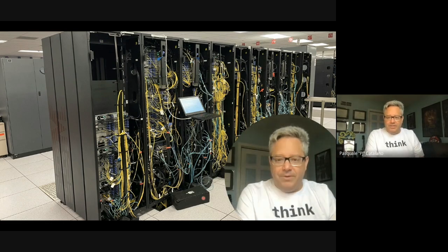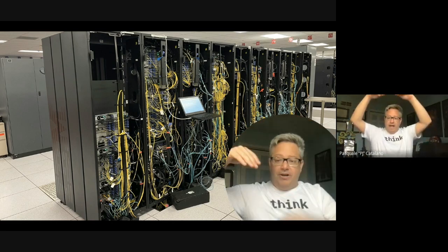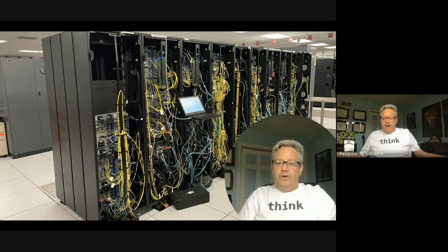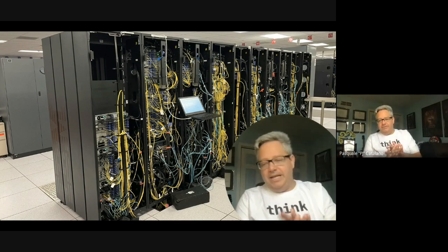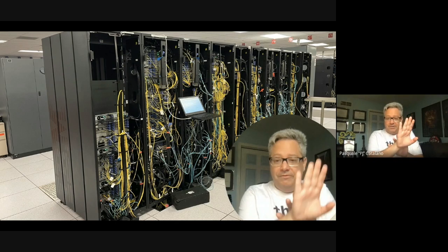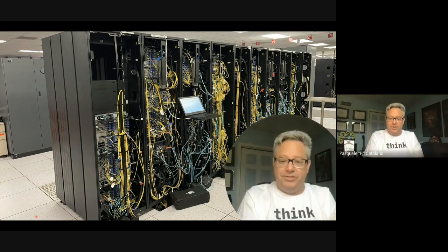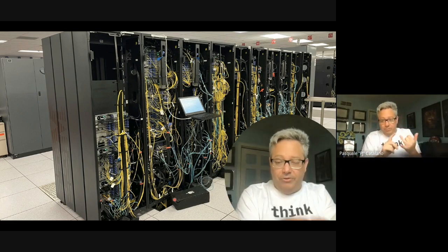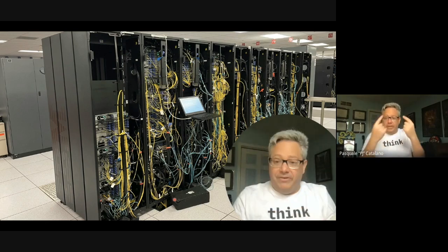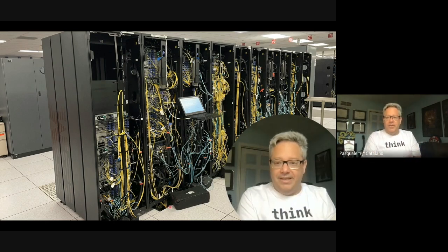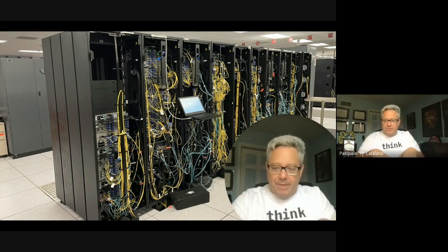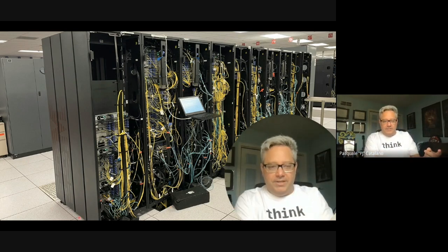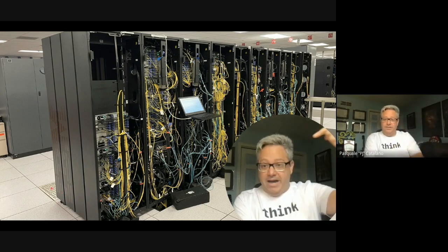The other thing I got to ask is, what is this brick here? Well, this is actually a fire retardant material. So I'm 30 inches off the ground. All my cables actually go down the floor and then route out. Well, in order to reduce any chance of, if a fire were to happen, we don't want fire to get air in and crawl up spaces. So this hole here, that brick, we would jam it in that hole to make sure that there's no airflow. One, it's fire retardant, and two, it prevents cooling loss, right? Because this is actually the hot side of the aisle. We don't want cold air coming out of here. So that also blocks the cold air coming out. You can see on the other side, it has those perforated tiles where the cool air comes out and comes in this way.